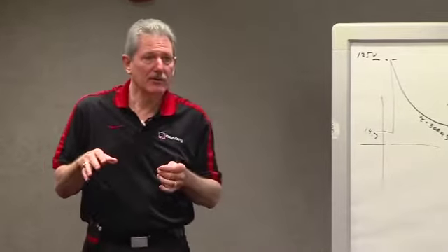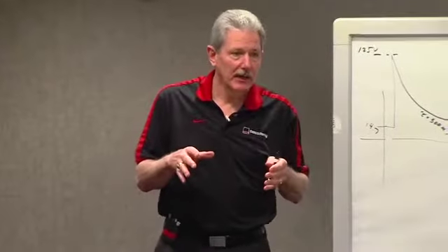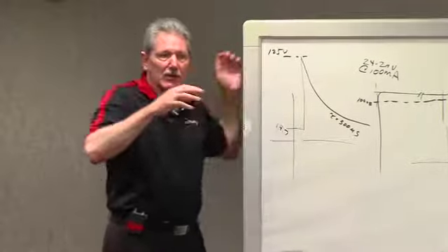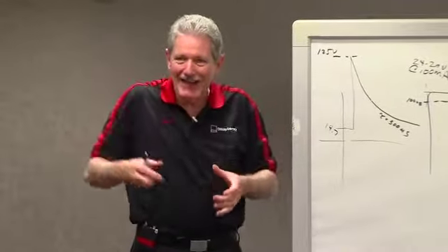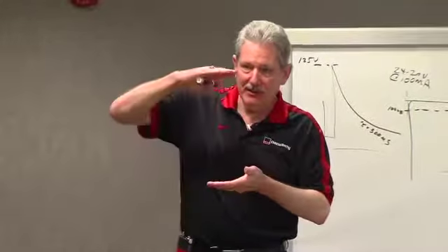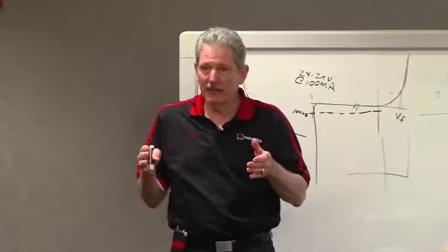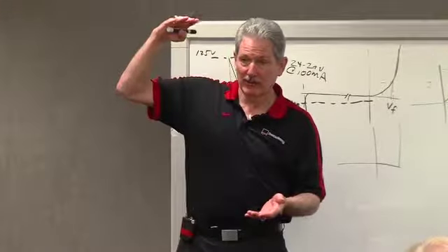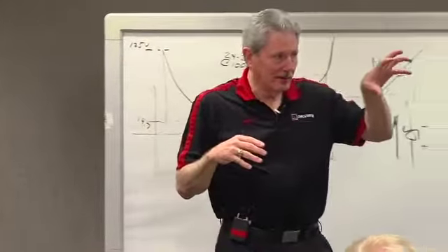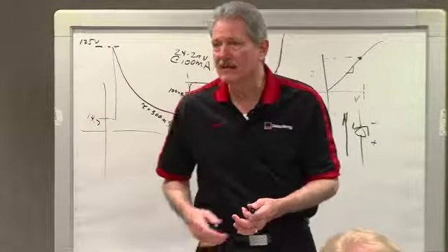So in 1985, Remy introduced the first centralized load dump protected alternator. In the old days, you had an alternator that would generate this load dump. So every place you had electronics on the vehicle had to have their own load dump protection. So all of the electronics had to have something that would clip that voltage down to a manageable level, because the cost of an electronic device is a function of the breakdown voltage. The higher the breakdown voltage, the higher the cost. So by putting load dump protection everywhere, everybody had to pay that money, 25, 50 cents.